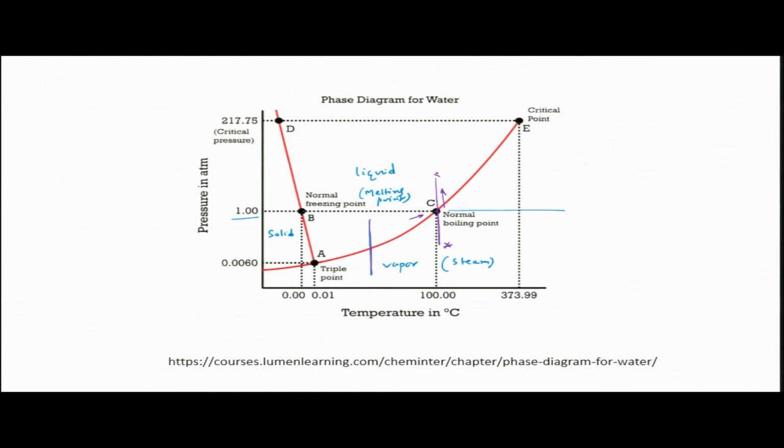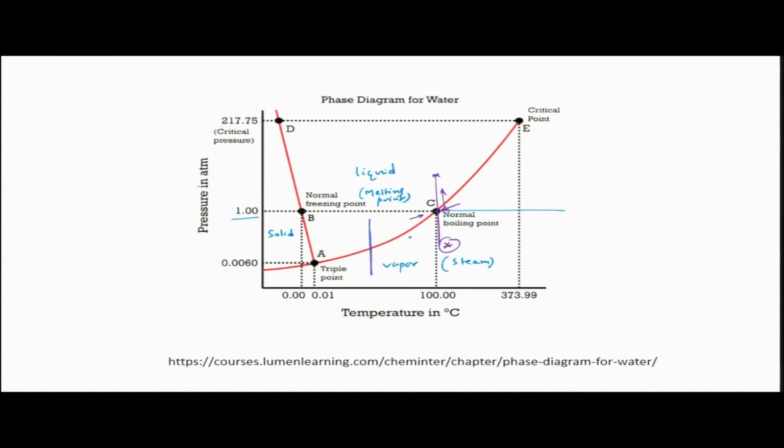Now, similarly, if we start from here and reduce the pressure without changing the temperature, at this location it will start forming small bubbles, and then once we get to this, it will be completely bubble. So, at this point we will not be able to tell what is the amount of bubble and what is the amount of liquid, and that bubble does not contain air, that bubble contains steam. Now, similar thing happens here, because this line is basically the liquid-vapor equilibrium line.